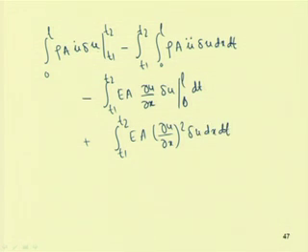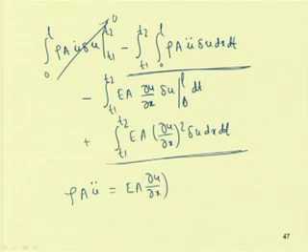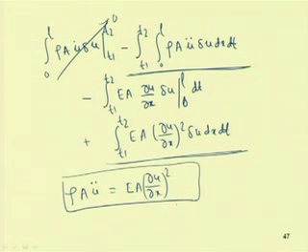We already know del u at T1 and T2 becomes 0, so that term becomes 0. For the equation of motion we add the integral terms, as del u is arbitrary. So, rho A u double dot equals E A del square u by del x square. This is the linear equation we obtained for this case, and the boundary term will give the boundary conditions.